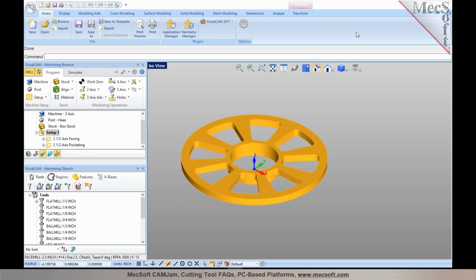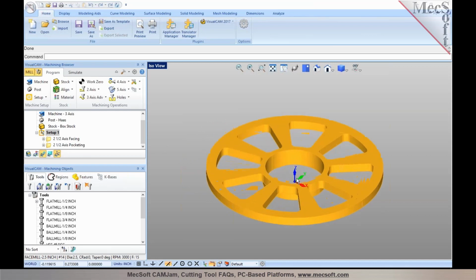So you've got to keep an eye on your non-cutting feed rates. Those are the areas where you can optimize it most, because most of the time the cutting feed rates are pretty much based on the material and the tool. And then, of course, as Uday pointed out, step overs and cut depths will affect the length of the overall motions. So these are the only two ways you can do it. So hope that makes sense.